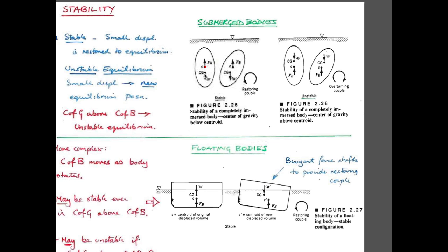And so if you take this stable structure and you move it somehow so that this center of gravity is moved to the left, and you leave it, then the couple, or the moment that's applied by this, is this force acting up through here, center of gravity pulling down here, and so they will tend to self-right. They'll self-align themselves. And so in this particular case, if you have the center of gravity below the center of buoyancy, then it's intrinsically stable.